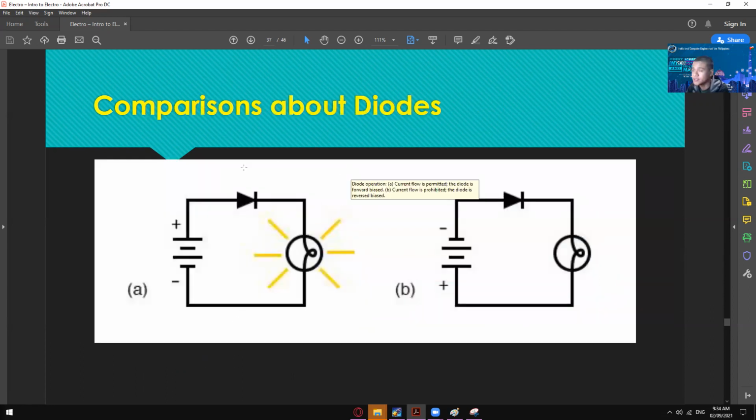Okay, so here's a comparison about diodes. So in forward bias, positive to positive, negative to negative, it has a flow of current. Okay, so our bulb is lighting up. And on the other way around, we have the reverse bias, which is negative to positive and then positive to negative. So again, this is similar with the no bias, because we have zero current on this part, because up to this point it's already not permitting the flow of current. So as a result, it wasn't able to light up this bulb right here.